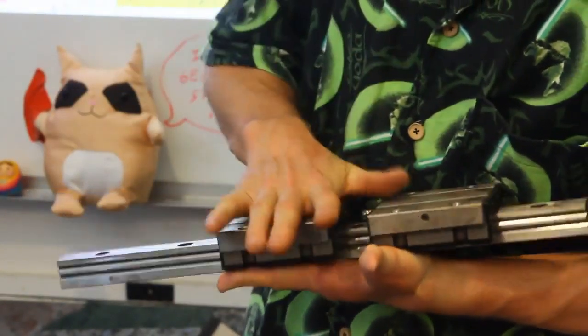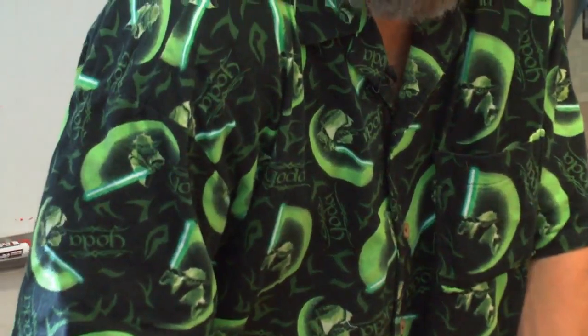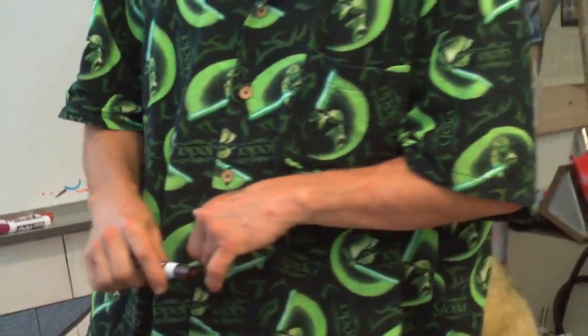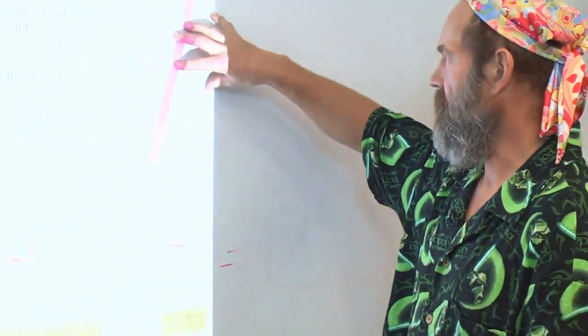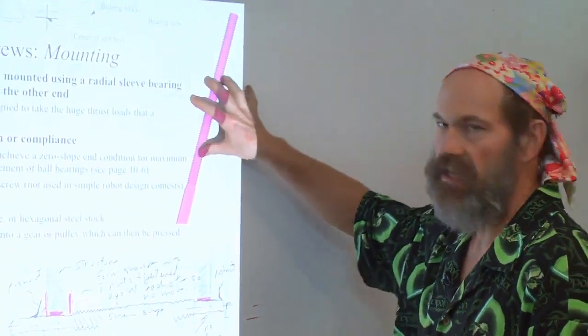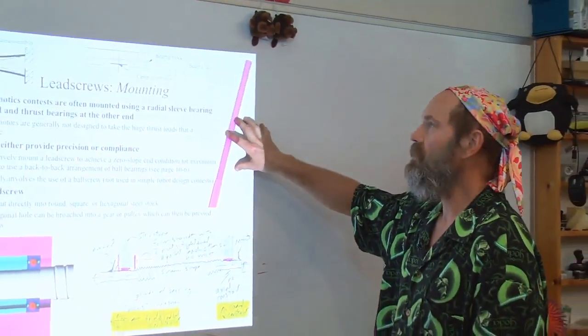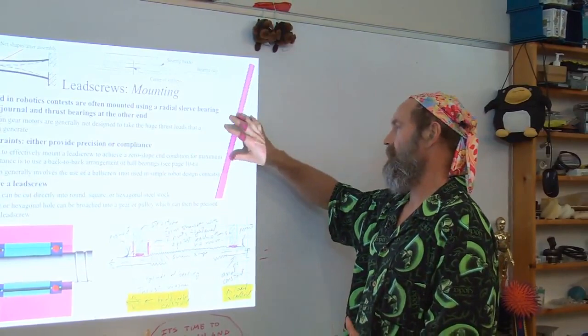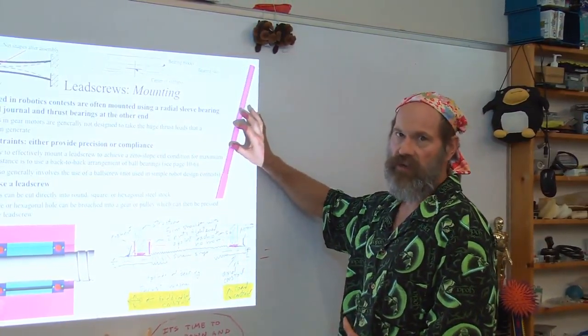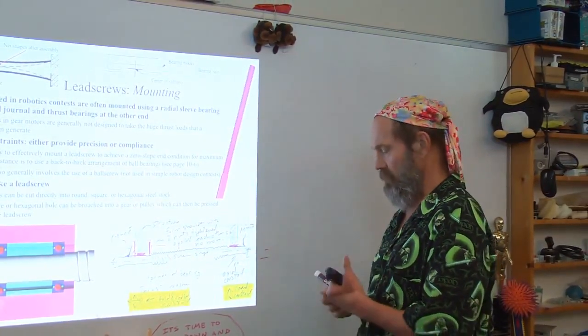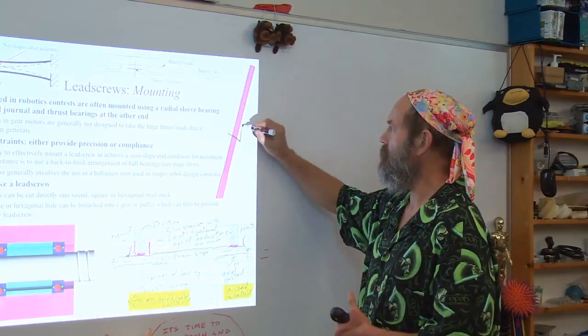But it's very, very stiff. Meanwhile, the lead screw attached to the carriage, the shaft is not so stiff. It's mostly stiff this way, but in bending it's not so high. So it'll tend to go along for the ride, but there will be some finite radial stiffness to the screw shaft.